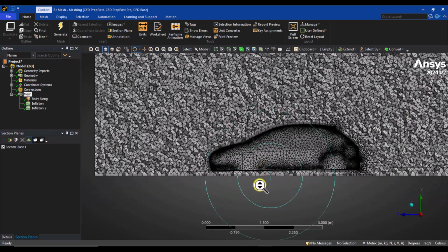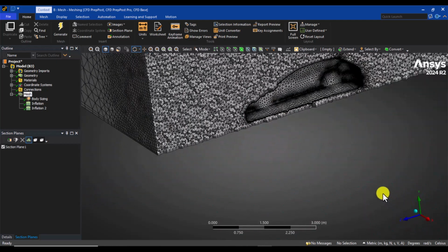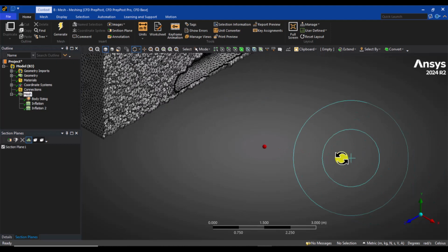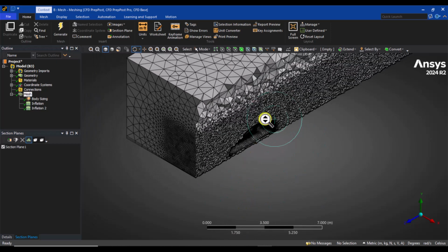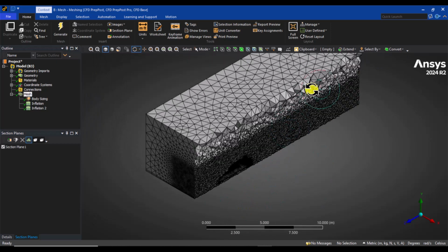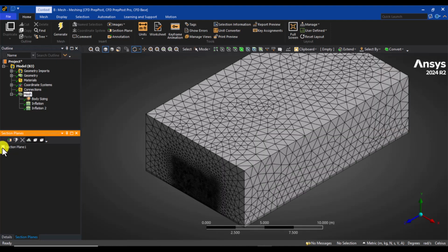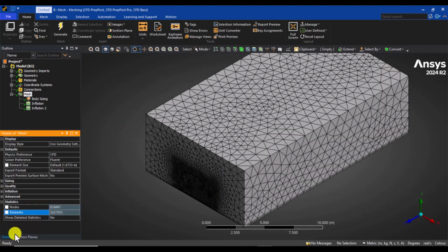So I can say the geometry model and mesh part is done, and there is one more thing left here, and it is creating name selections and names for each of these boundaries, so we can use them in our model later on. So I uncheck this box to have the full view and get back to the detail stuff, and we are done with the mesh part.